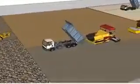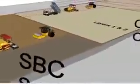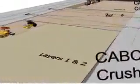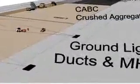Level control is maintained by 2 string lines as a grade reference system for the lead paver, and a matching shoe and 1 string line for the following paver. The pavers operate using an automatic screed control, which controls the screed height using the string line or the matching shoe as a level and line reference.